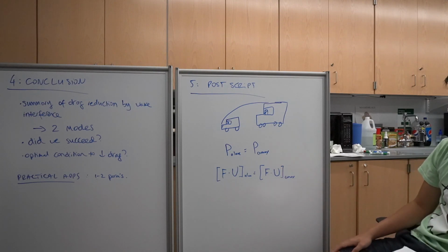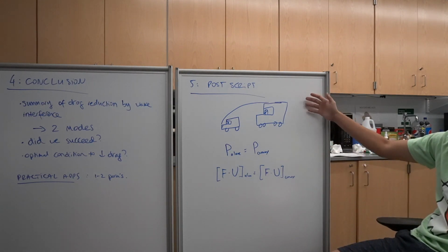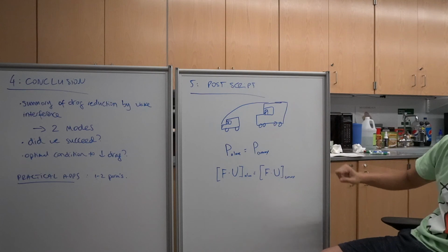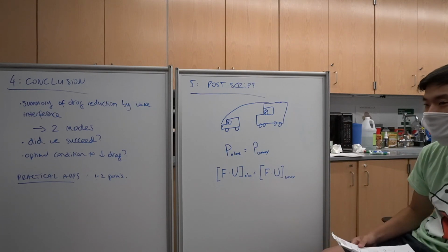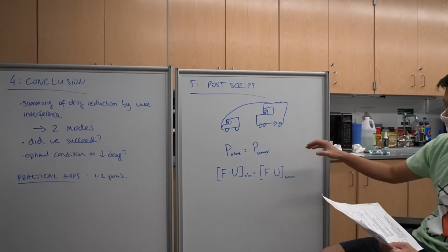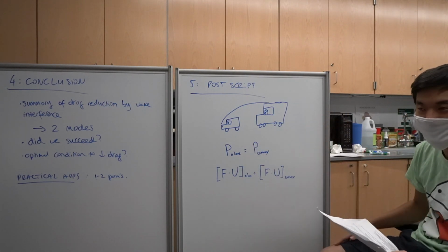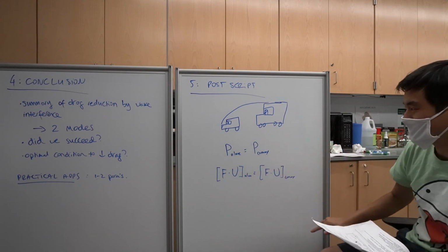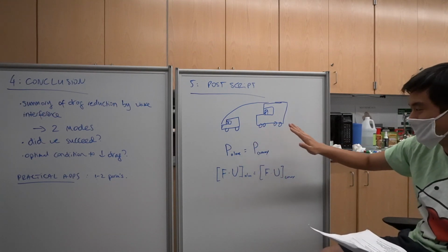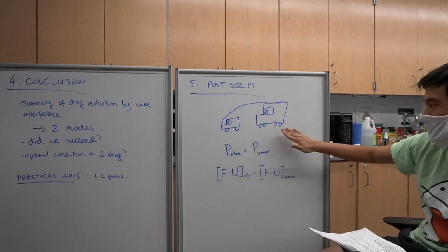So use this to calculate what the new velocity would be, assuming that you're in the convoy outputting the same amount of power. So the assumptions are that this car in front is conveniently 37% the height of the truck, which we have data for, and then also the distance between the car and the truck is always spaced such that the drag is minimized on the truck.